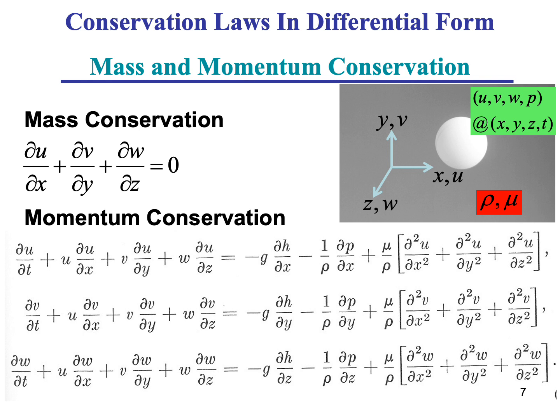Our dependent variables would be the velocity of the flow in the x direction, which we call the small u, and the velocity of the flow in the vertical direction, as well as out of the page. So u, v, and w are the three velocity components of the air that's in this domain, in the x, y, and z directions, respectively. Eventually, there is a fourth variable, which is the pressure, as you can see here. So now we have defined our dependent variables, which are u, v, and w, and pressure. And our independent variables are x, y, z, and obviously we have time.